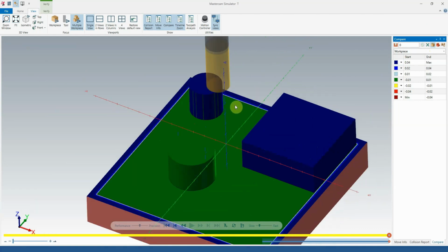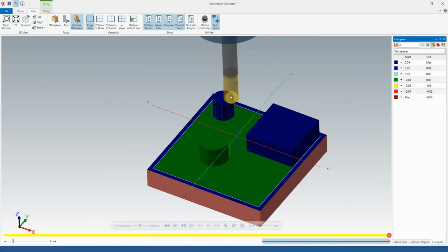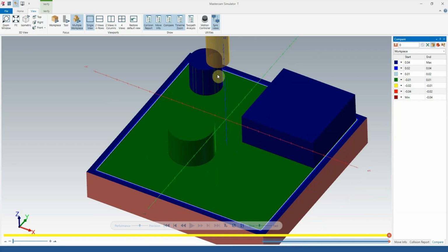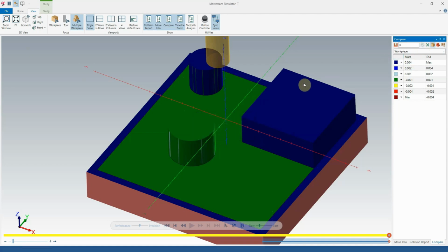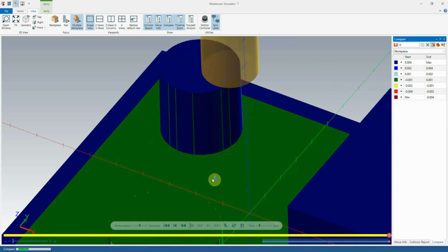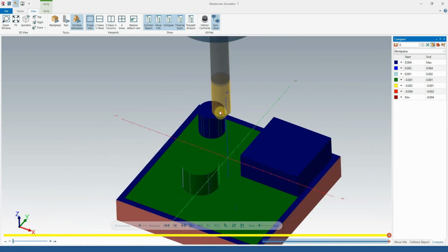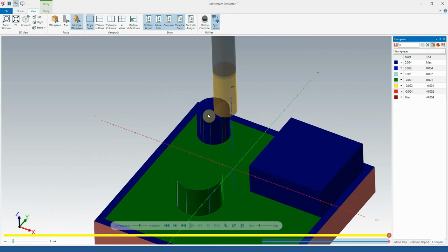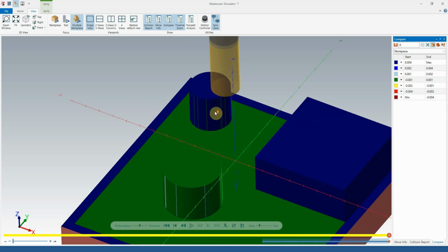Now, something to take note with Mastercam, it has a few different simulator options that will affect the accuracy, especially of the compare tool. If I put this back to 1 thou, say OK, refresh, you'll notice that, for example, it's saying there's stock being left on this island, even though we told our cutter to cut this to the finished size. What's happening here is that Mastercam has two different simulators. It has the 3-axis or 5-axis simulator. And for some reason, the 3-axis simulator doesn't simulate cutting walls very well.